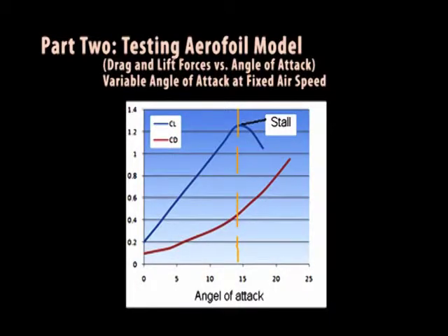The results should be presented on a graph showing the drag and lift coefficients versus the angle of attack, with clear indication to the angle of attack at stall. As you know, the stall occurs at a certain angle of attack when a loss of lift force is accompanied with an increase in drag force.